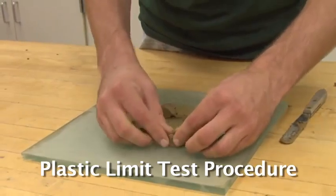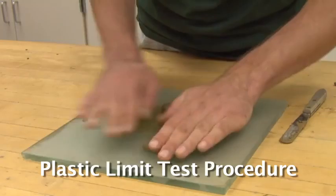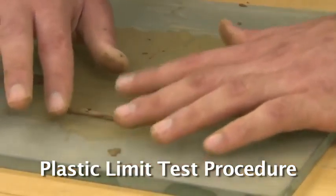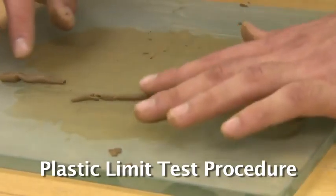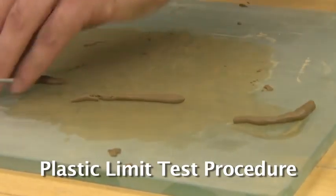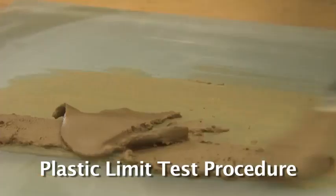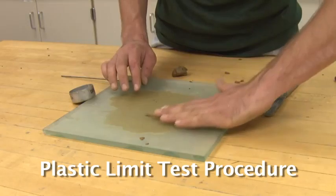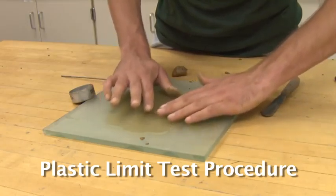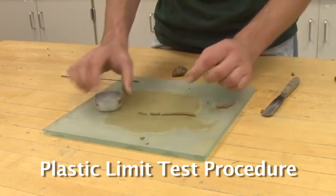Start rolling the soil into a thread. Roll the soil until the diameter of the thread is reduced to 3 millimeters. The rod can be used as a gauge to determine when the soil has reached 3 millimeters in diameter. If the soil does not crumble when rolled down to 3 millimeters, further dry out the soil and try again. Once the soil crumbles at 3 millimeters, collect samples of the crumbling soil and place them in pre-weighed tare cans